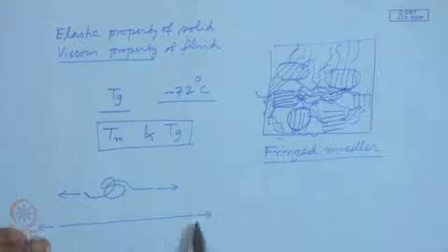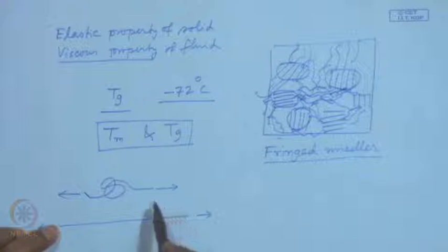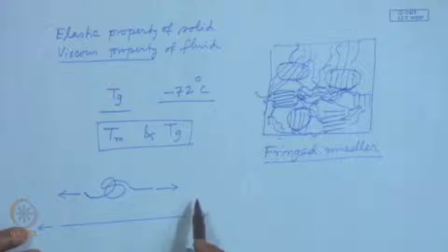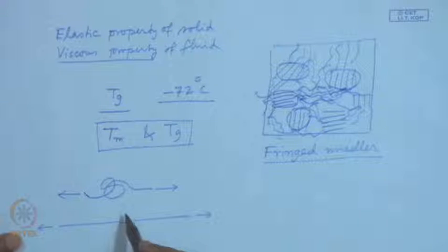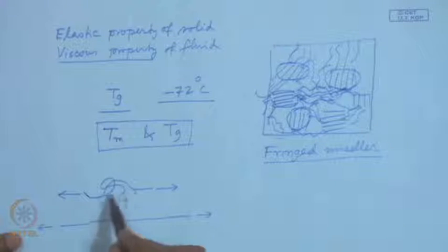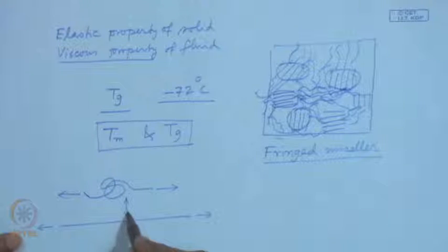Now, such elongation, up to this deformation, we can consider that in case of an elastic system, is instantaneous, it is not time dependent. Now, when stress is released, it should come back to this original configuration. So, this is a reversible phenomenon.